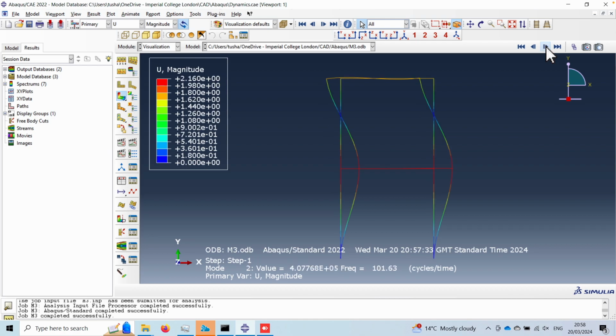second mode. Okay, at least the mode shapes you can compare, right? The mode shapes are quite similar for the first two modes, but of course there is a deformation here. But yes, you will observe other modes, because of the deformation flexibility of these members. So these are all different mode shapes and the corresponding eigenvalues are also given.